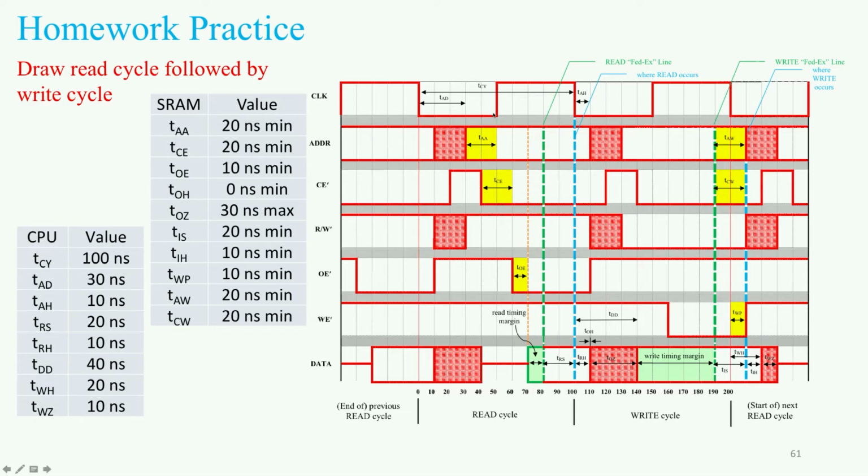Then finally the clock goes to a high state, and 10 nanoseconds later, there's a delay, and then the output enable bit is updated to reflect the fact that the read bit is asserted. So then it flips down, effectively telling the memory that it should output something.